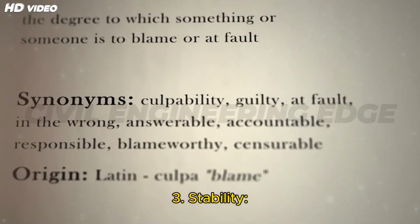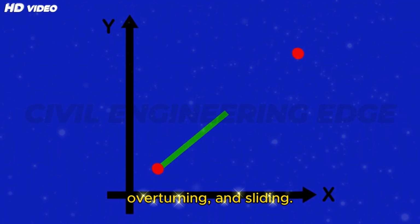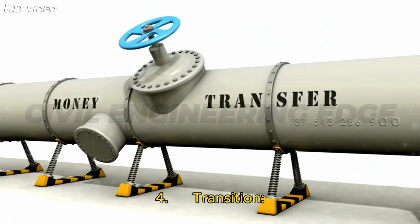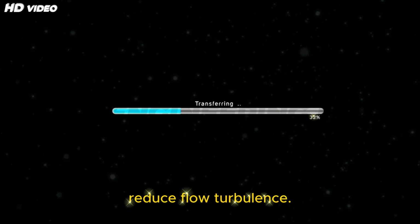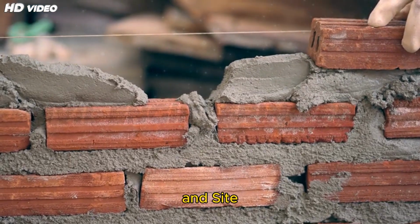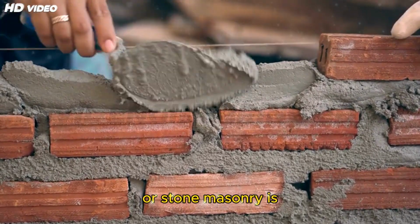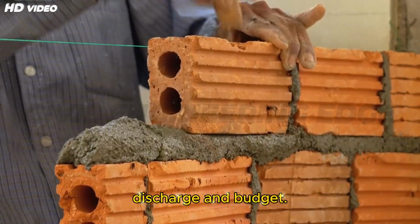3. Stability. The structure must resist uplift pressure, overturning, and sliding. Aprons and curtain walls are designed accordingly. 4. Transition. Smooth transitions inlet and outlet reduce flow turbulence. Transitions should follow curves to minimize velocity spikes. 5. Material and site suitability. Choice of RCC, brickwork, or stone masonry is made based on soil conditions, discharge, and budget.